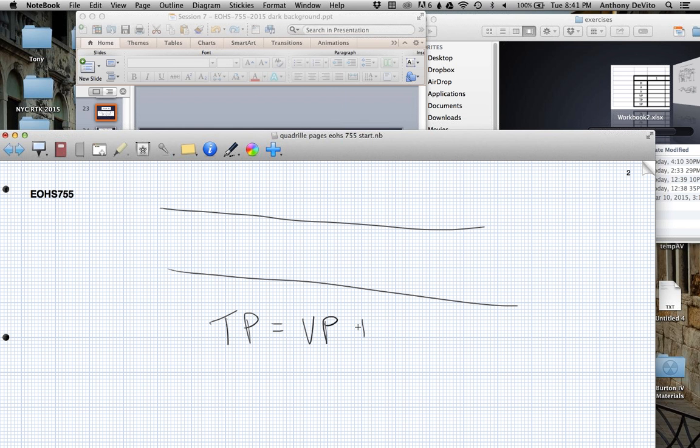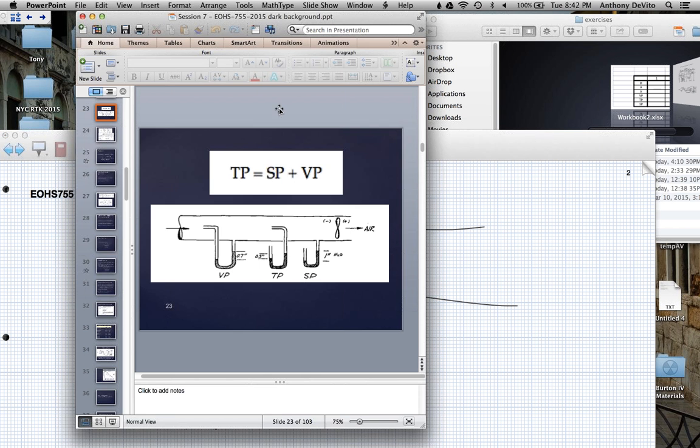Okay, so now total pressure is equal to the velocity pressure plus the static pressure. I changed the order, but it doesn't matter. What was the total pressure again? It was negative 0.3. And that's equal to the velocity pressure, which we don't know, right? But we do know the static pressure, and that was -1, right? So what does the velocity pressure have to be? Going to move +1, right? What's the velocity pressure equal to? 0.7, right? The velocity pressure is a positive number, right?